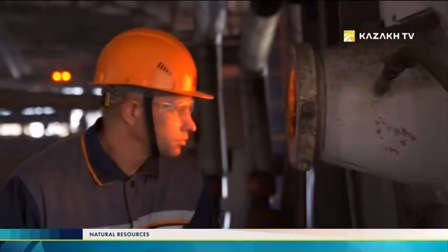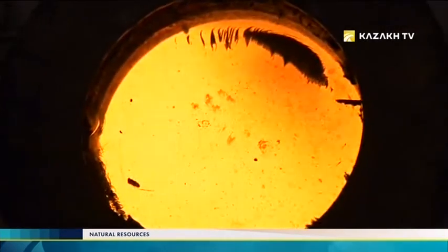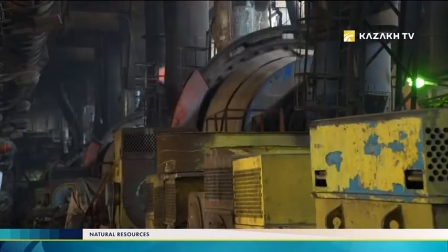Other countries widely practice processing of high-quality bauxites. There, red mud is considered as waste that should be disposed. In our case, red mud is processed, and useful components are extracted during the sintering stage. It is the sintering method which Pavlodar metallurgists use to extract aluminum from mass that are about to be disposed.